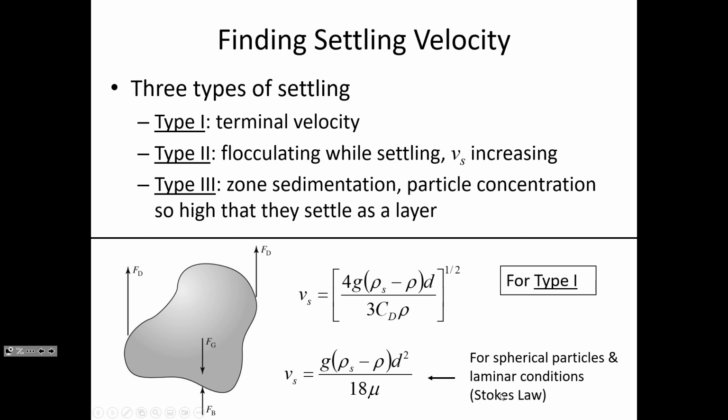in a flocculation basin. Some of the particles won't be spherical, and those particles will settle at a different velocity than is predicted. And so this model isn't perfect in predicting what's going to happen inside of the settling basin, but it does a fair job, and its simplicity is hard to argue with. And you'll notice that the viscosity also is one of the terms here. The viscosity of the fluid varies as a function of temperature, and that'll usually be given to you in a problem statement, like which viscosity you should use.